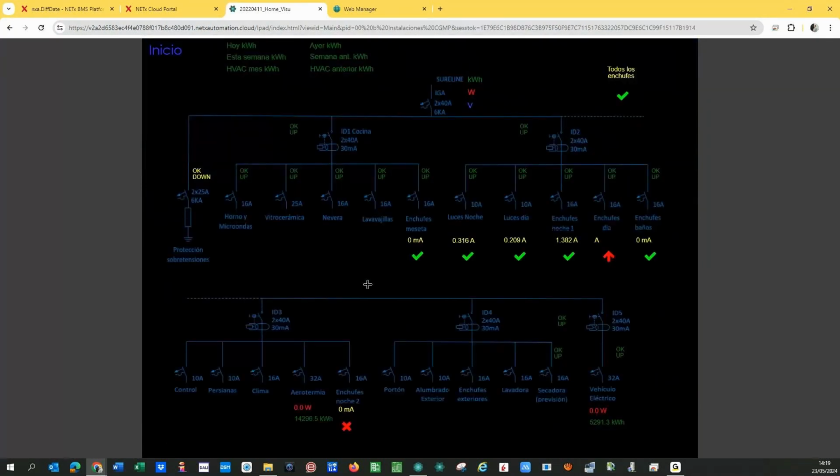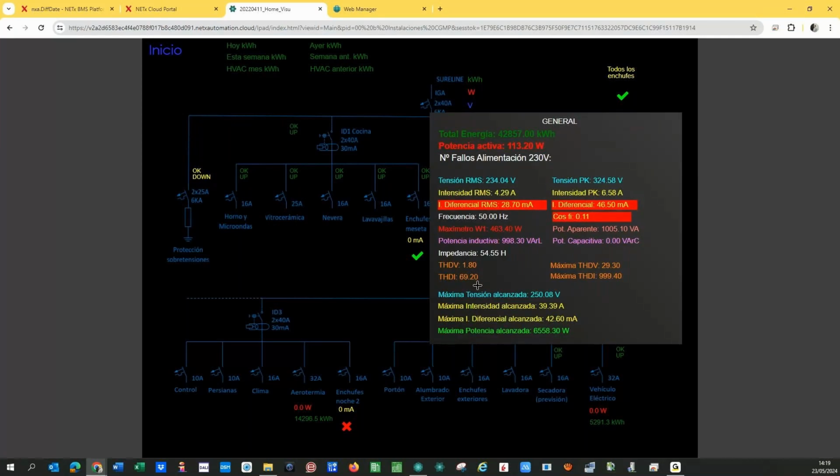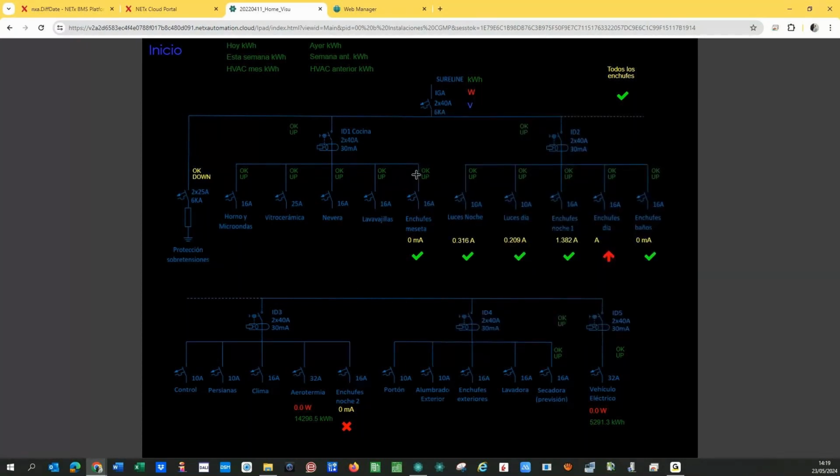And the electrical board, where you have a lot of information from the Modbus elements. I told you that we have a lot of things, some other information from the protections, if it's okay, number of cycles, number of triggers, the hours of all these elements, differentials or direct protections. You can also change some protections that are in serial with a binary actuator, so I can act on these elements also. I can get information from any of the protections directly, so it's possible.